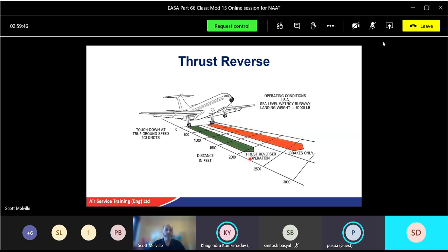Yeah. The stress due to the aerodynamic and centrifugal or thermal. It's more, just think of the blade stretching, the centrifugal force. It's going to bed in, and eventually because of the centrifugal force, it's going to stretch the blade. So we call it stretching, we call it blade creep. It's creeping away, it's getting further and further away. So remember, we've got primary, secondary, and tertiary.